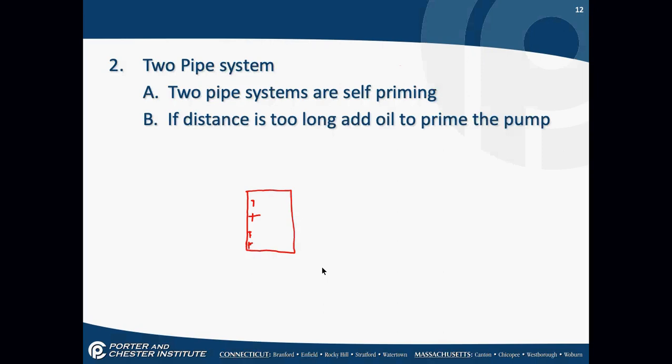But once my oil burner is started, what can I do to this primary control to make it think it's seeing light? Do you jump F and F? Exactly.